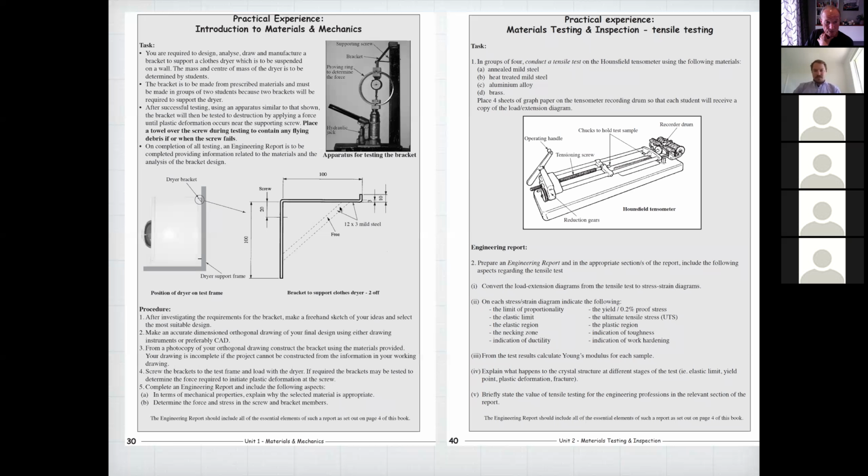And of course, lots of students would, you know, put the strut down here, stick it out there like that. And then I'd either weld it. Yeah, that's what I used to do to save time. I just used to weld the strut on, and I didn't tell them how to position this strut or anything. And when the students put it on the flat, it failed very quickly. But the students with a bit of nous, they twisted it to increase the toughness of it.